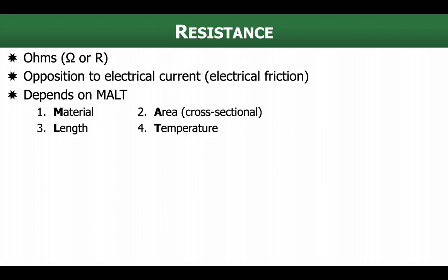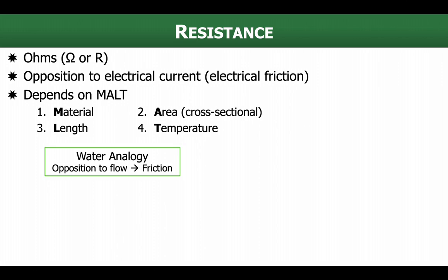How long is the wire? If I've got to go a long way, there's going to be more resistance. And then materials, temperature causes different things to happen. Temperature goes up, resistance goes up. So the temperature is going to have an effect as well.